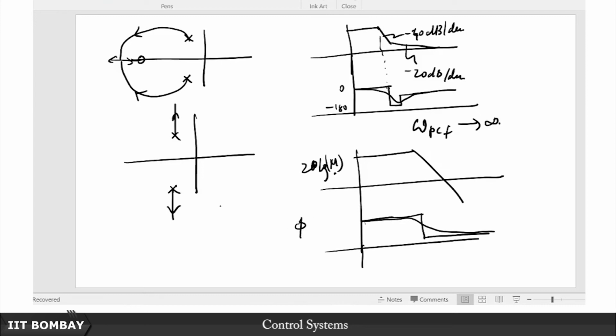So, whether it is a second order system with a 0 or a second order system without the zeros, you see from the root locus that this closed loop pole never migrates to the right half plane. I am claiming that an understanding of phase margin and gain margin will still allow me to infer the same thing about it, even if I forget about the left half of this slide. How so? So, here is the point.